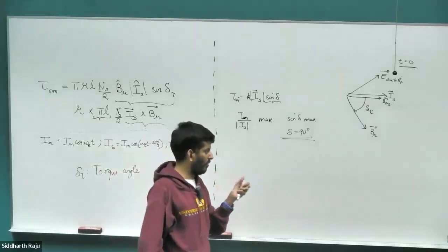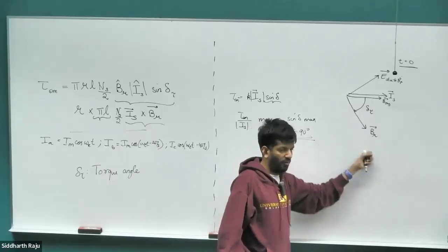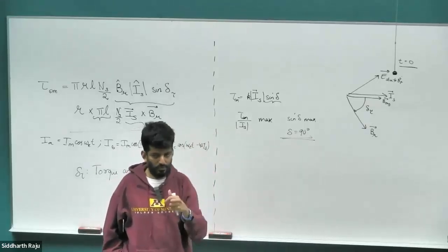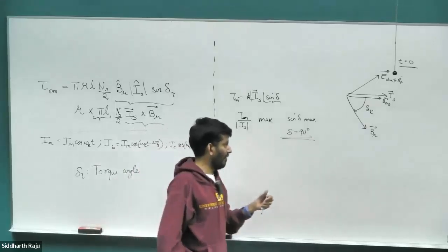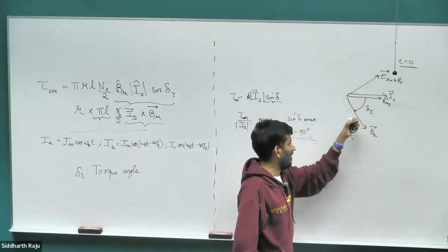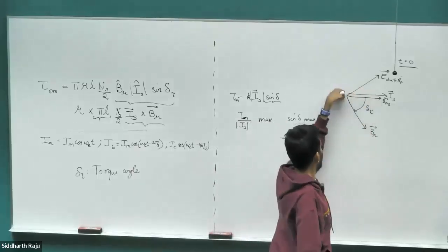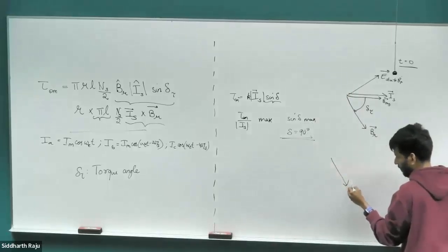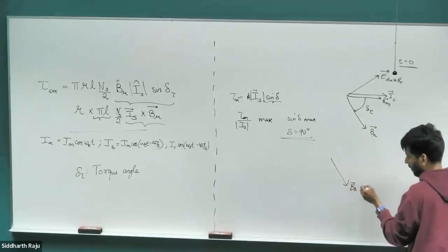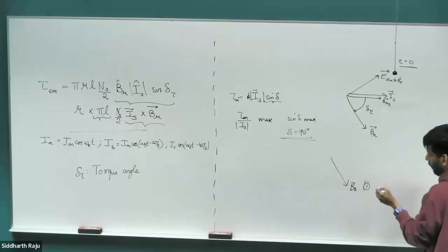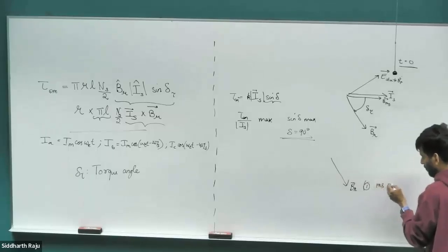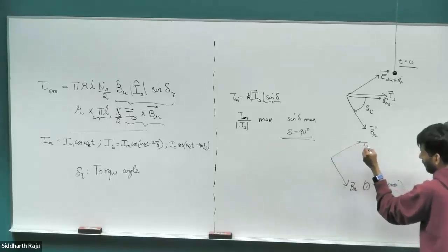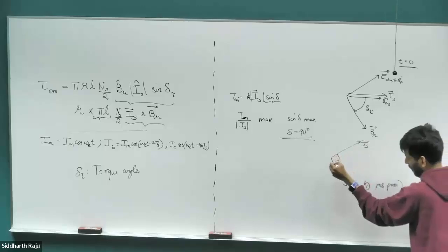And you would mount it such that the absolute zero position would be pointed along the direction where the rotor magnetic field is at its maximum. So you know exactly where the north pole of the rotor magnetic field maximum is at any given time. And then you would have your drive inject currents into the motor such that the space vector is 90 degrees away from it. So first you would start off with measuring the rotor position, which would tell you where the rotor magnetic field space vector is pointed. Right? Measure position. And then the second thing you would do is inject current such that the current space vector is 90 degrees away.